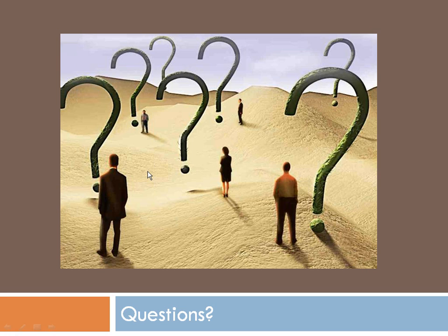You mentioned the BCRA tile changed color under different temperature, humidity conditions. Did I hear that accurately? Yes, you did. I mentioned the red BCRA tile specifically because it was a worst case. But any physical object changes its interaction with light when its temperature changes, whether that's noticeable or not. The neutral BCRA tiles, the other color BCRA tiles, are less sensitive to temperature and not particularly sensitive to humidity as long as their surface is intact and they're properly sealed where they're cut.